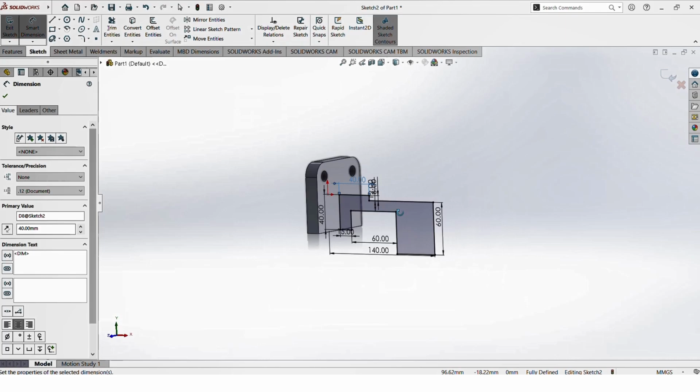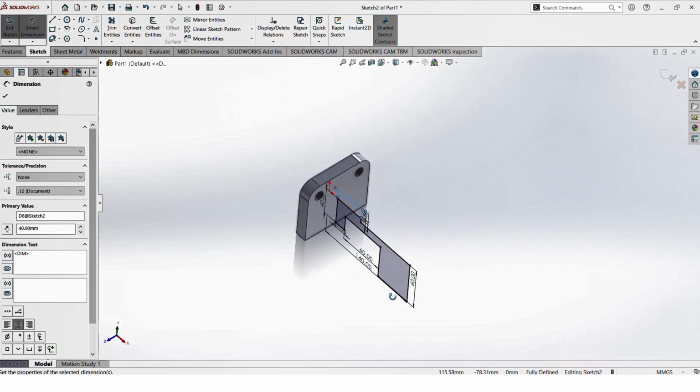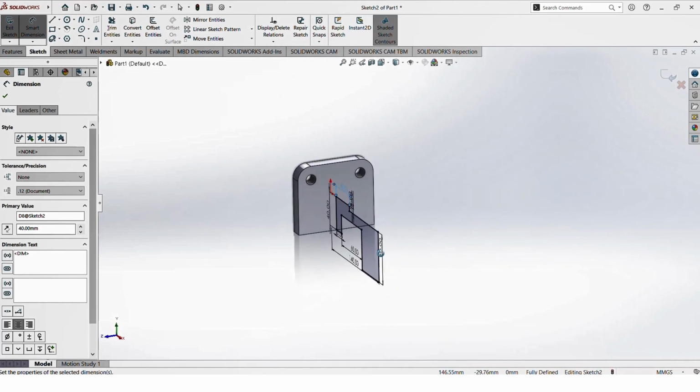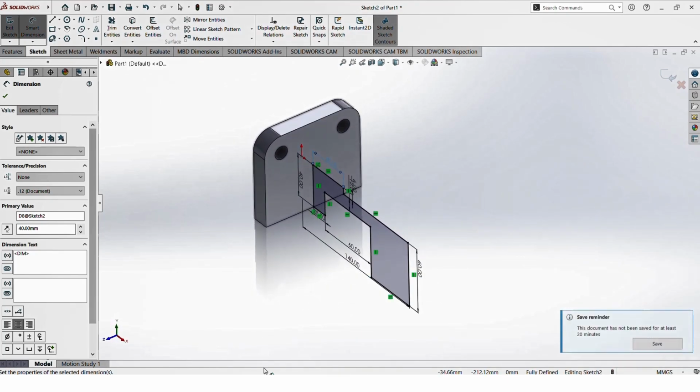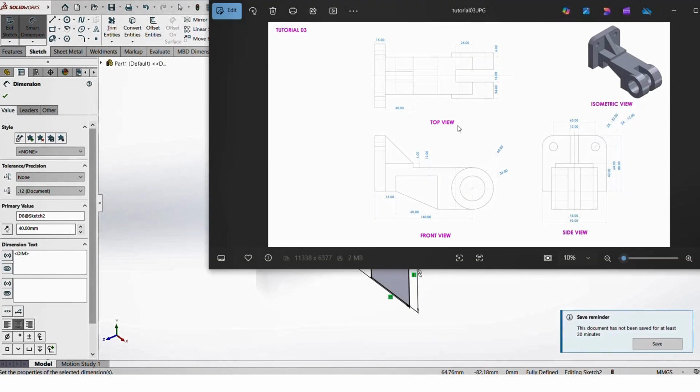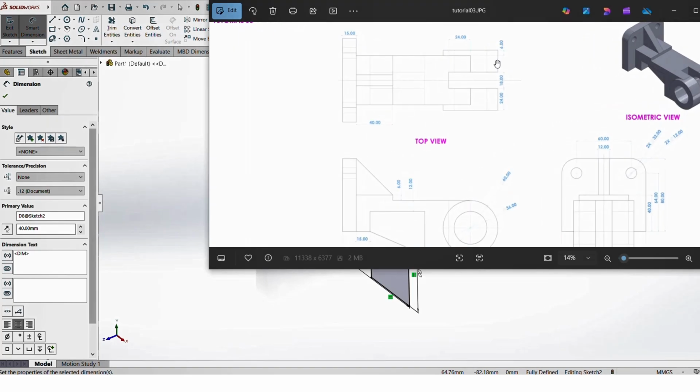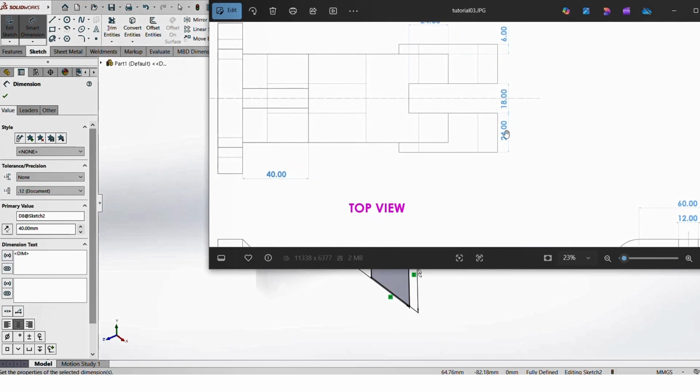The sketch is drawn in the front plane, which is the middle of this model. Now the sketch is in this condition, these positions. Extrude in both directions, half. Up to this portion you have to extrude. The dimension is 24, subtract this 6 millimeter, now it is 18 millimeter. Again this gap is 18 millimeter and the remaining portion is 18 millimeter. So extrude up to 3 times 18 millimeter.